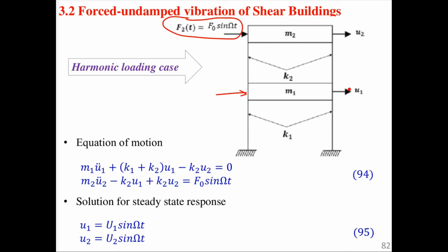But now for us to understand bit by bit, we are considering only the part that contributes to the kind of analysis that we want to conduct. In this case, the dynamic analysis brought about by the lateral forces. So now the equation of motion, I hope you remember the equation of motion that we had, the M matrix, and then we'll have the acceleration as a vector, Mü plus Cu̇. Last time we did not include C, and even now we are not including C because the damping is not yet a consideration. The square bracket, and then the velocity will be a vector.